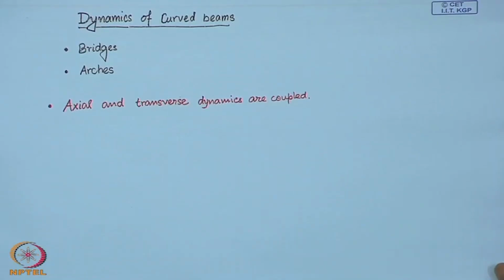We had made some simplifying assumptions when we formulated the dynamics. We assumed that the beam is still planar, though it is curved in a plane. We assumed that the deflection is much smaller than the thickness of the beam, and the thickness in turn is much smaller than the curvature, which was assumed to be a constant.